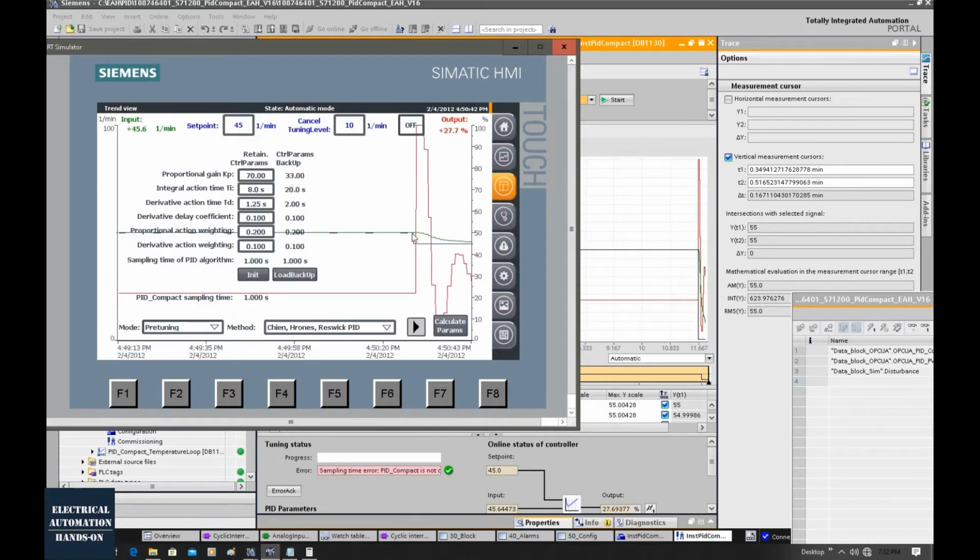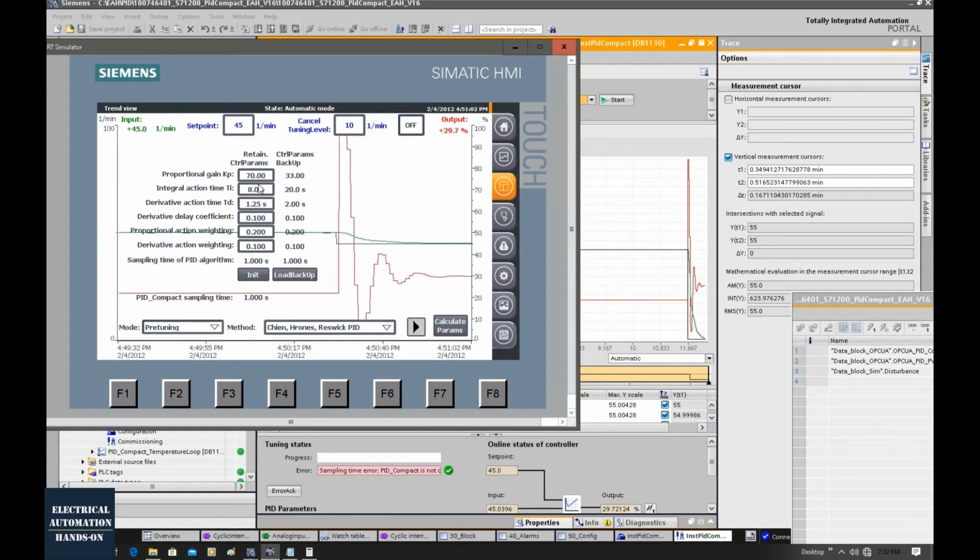Before this fine-tuning, most of the time we already have rough PID parameters. That means your current PID parameters might work fine, but cannot work perfectly. So using the PID auto-tuning can give you a better group of PID parameters. Before we run the fine-tuning, we had better write down the current PID parameters, in case the fine-tuning gets an error or fails, so we can still use the recorded PID parameters to recover them. When the system has reached its operating point and is working stably, we can start the fine-tuning.